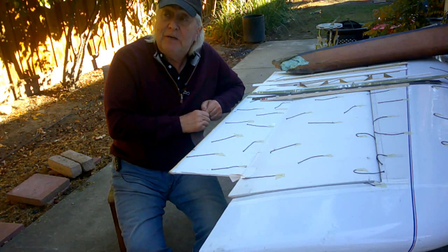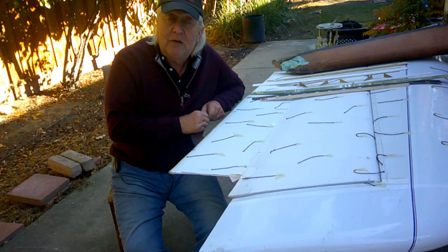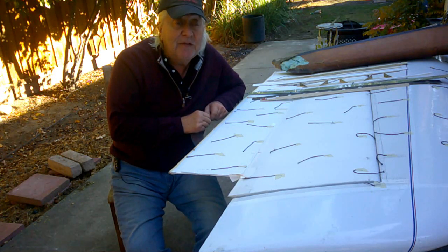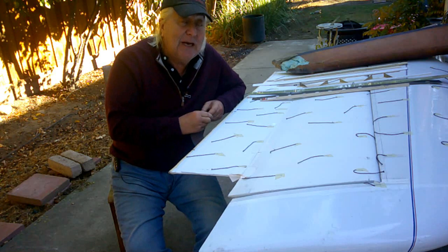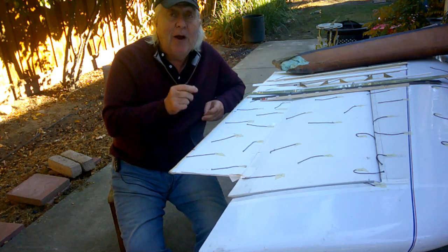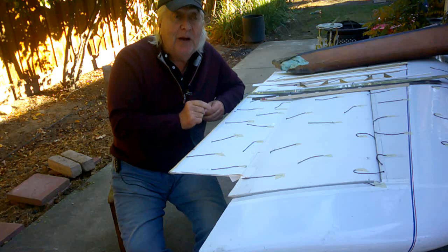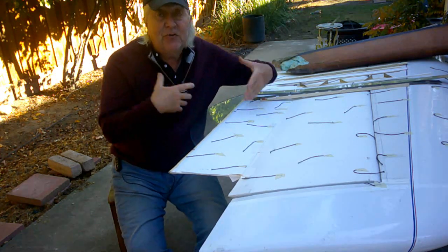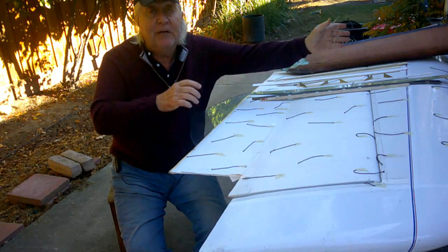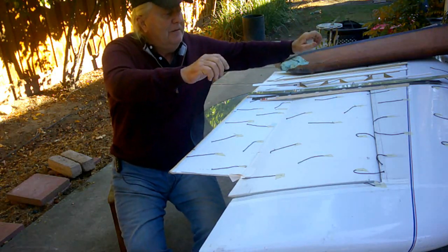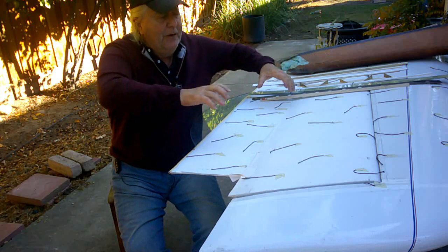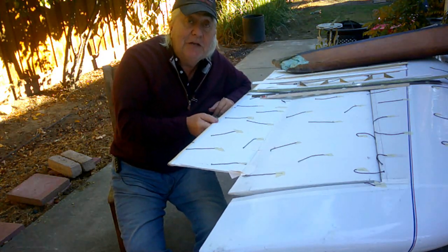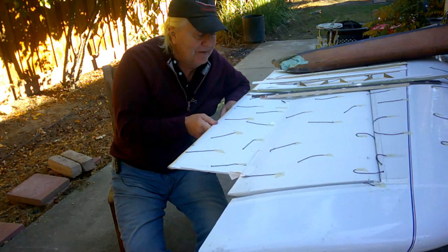So, I think, you know what? The Millennium's the same. Why is it the same? Oh, well, when you stop and think about the whole problem, okay, I want rigid wing performance, but I want it in a package that I can fold up. So that just drives you to D-tube, folding ribs, fabric, take it apart, fold the ribs, roll up the fabric, go home. Right. What do you do with the rigid elevons?